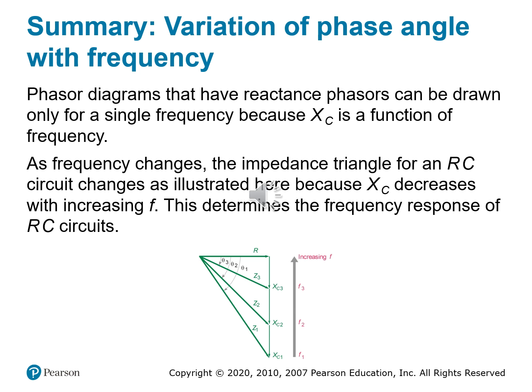So capacitive reactance, we know, depends on frequency. And let's start off with the truth at the heart of it all for RC circuits. X sub C is equal to 1 over 2 pi F C, which is 2 times pi times frequency times capacitance. And this tells us that as frequency F increases, the capacitive reactance X sub C decreases. And when X sub C shrinks, the shape of the impedance triangle shifts.